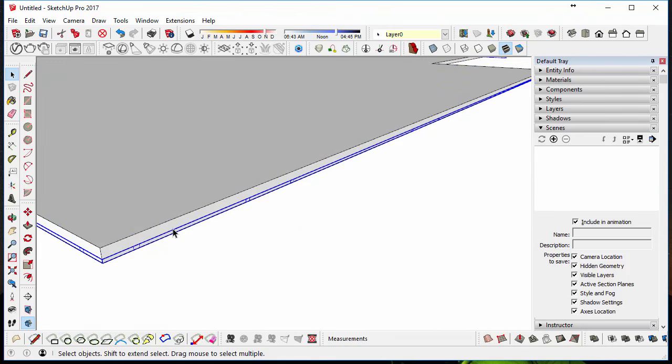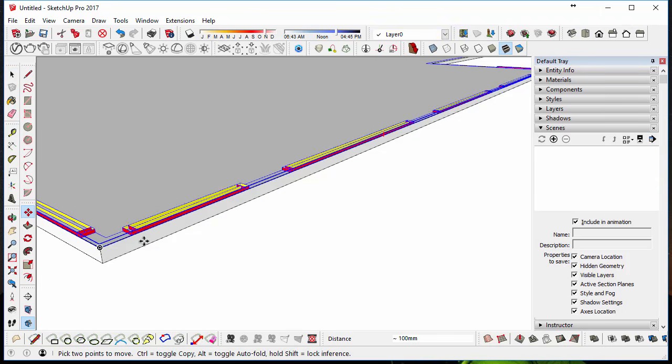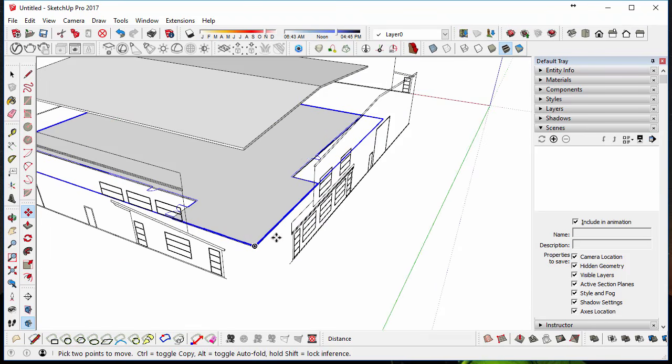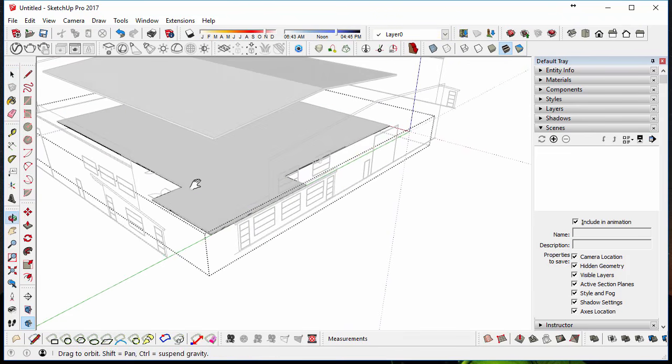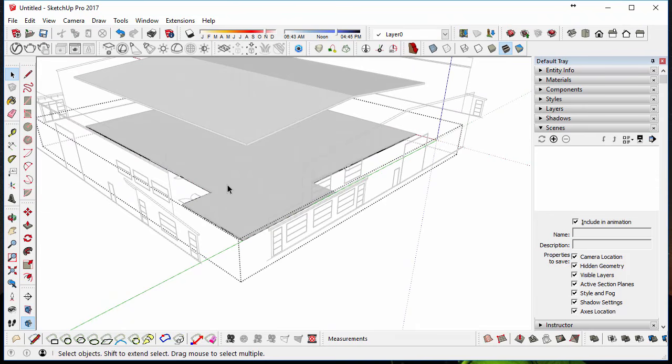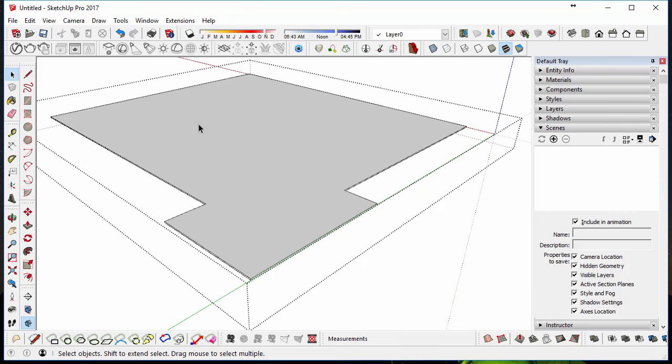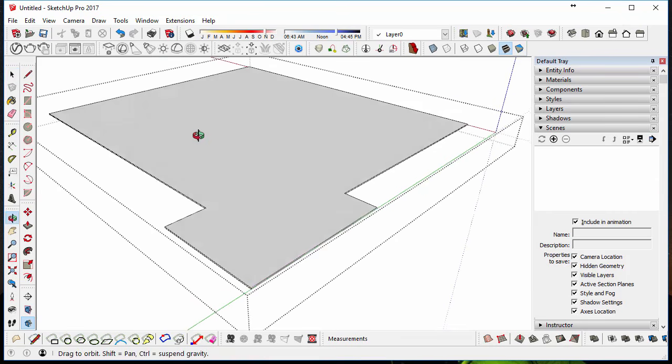Now I'm going to select the floor plan and move it upwards, so it's just back on top of the foundation, so I can just see where the doors are and things like that. And now I can draw my walls. So what I might do is just edit the foundation group, press H on my keyboard, which hides everything else, and that's again a quick key that we learnt in the previous tutorial how to make.